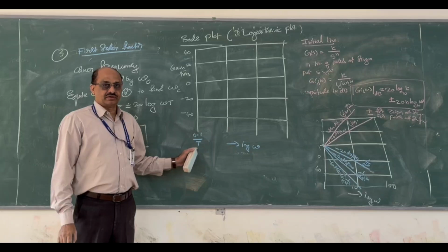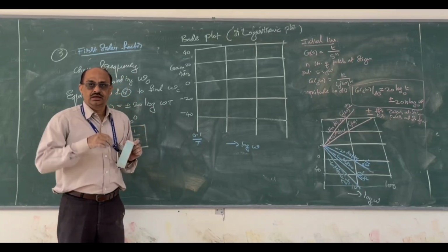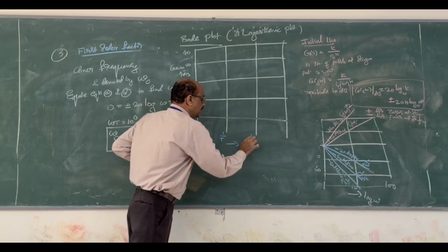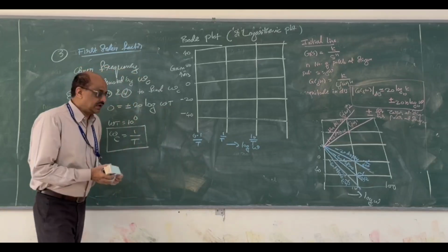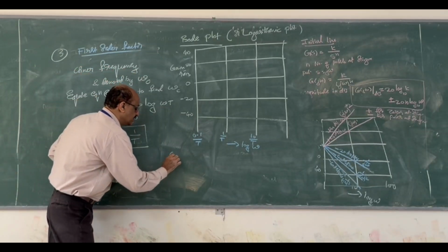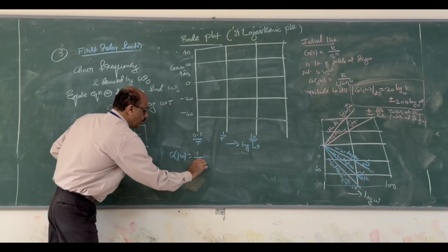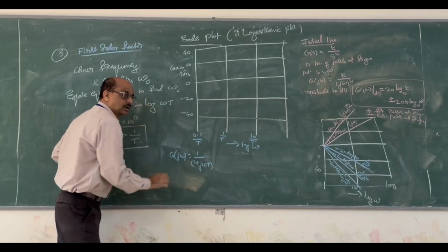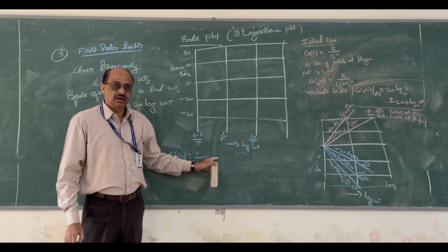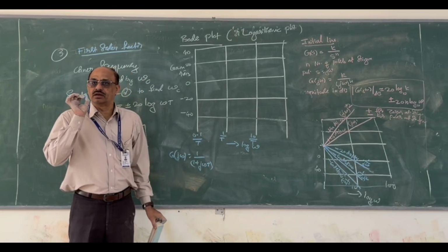I start with the frequency 0.1 by t, then 1 by t, then 10 by t and so on. So it is telling you that for one pole, G of j omega, if I have this 1 plus j omega t, this has a corner frequency of 1 by t, and a slope of minus 20 dB per decade.